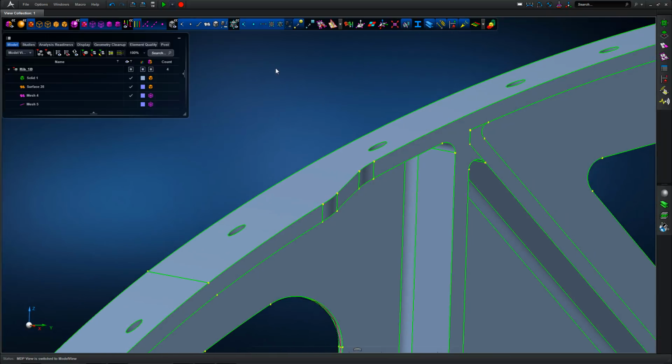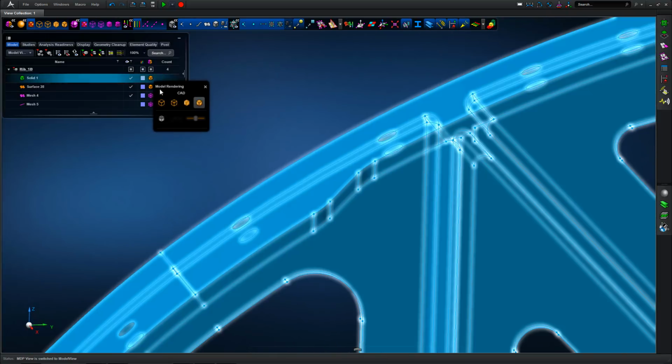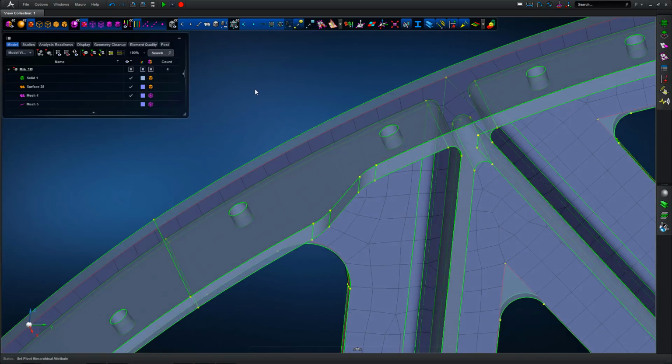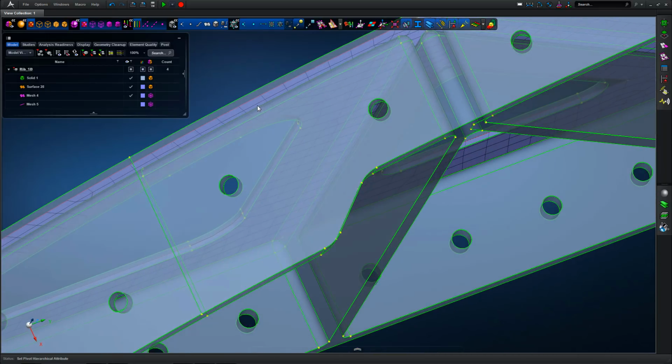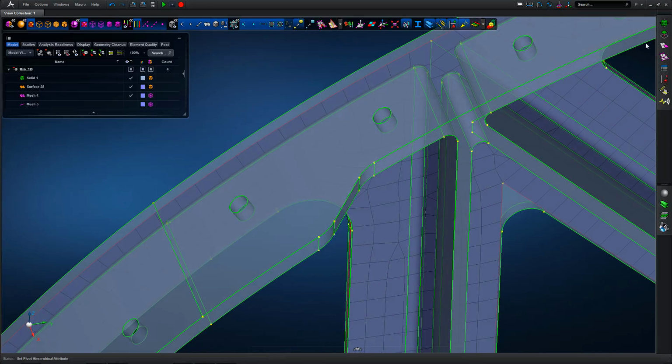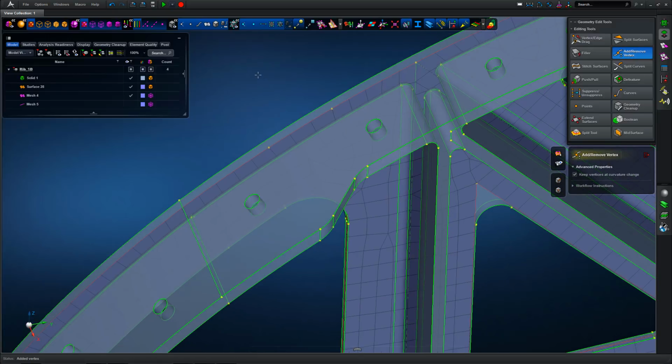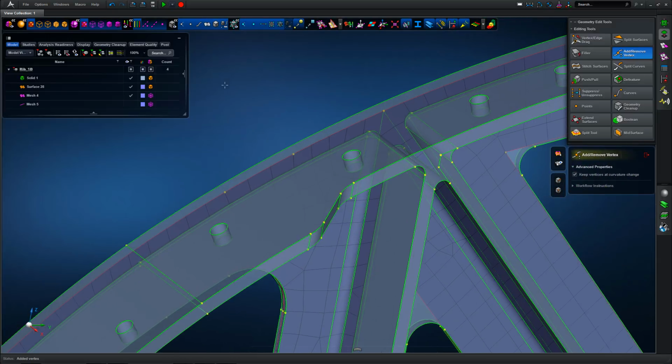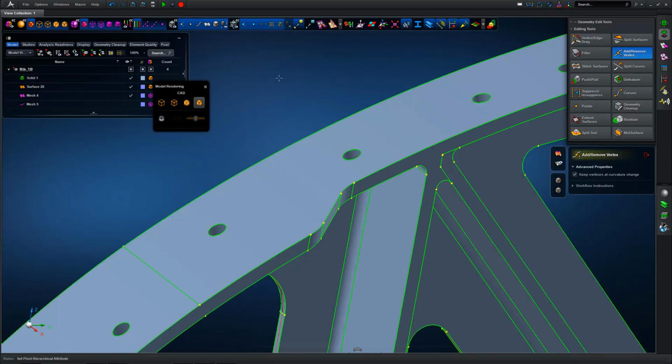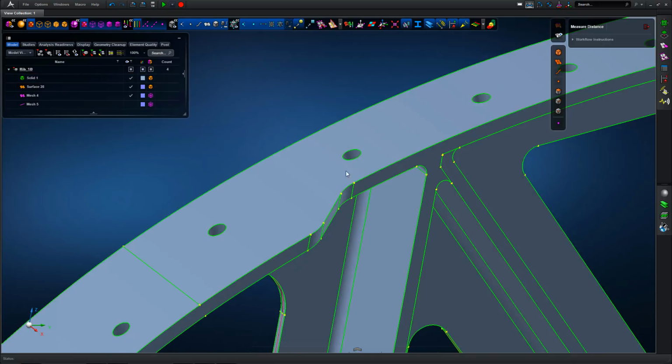Looking at some of the underlying CAD definition in terms of the rib and stiffener geometry, going into wireframe or transparent mode for the CAD definition, we can see how the flanges will sit against the underlying mesh topology. So we're putting some vertex or hard points into the mesh to give us a transition where we can see the rib flange spreading outwards. We're going to define a series of different 1D beam properties to give us the idealized 1D beam stiffness that we require.